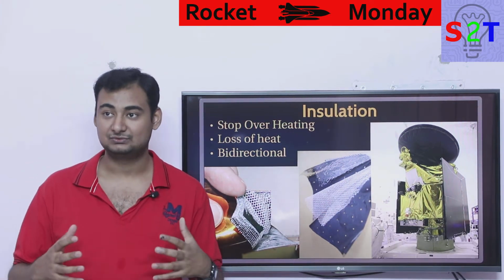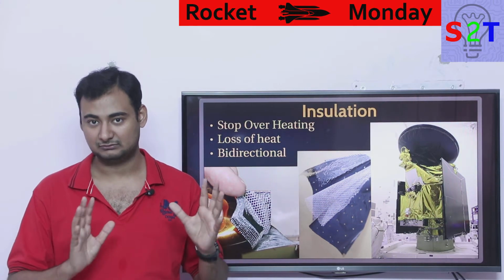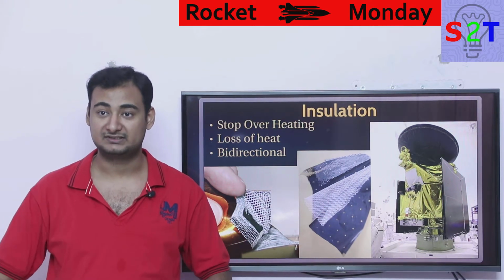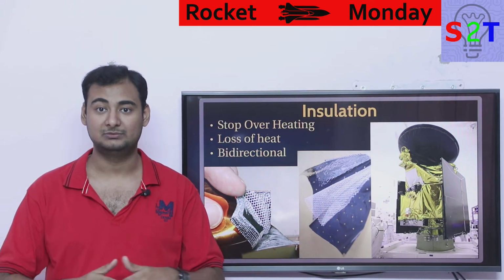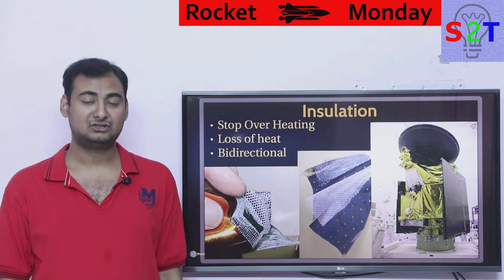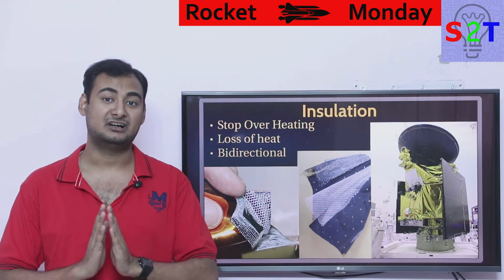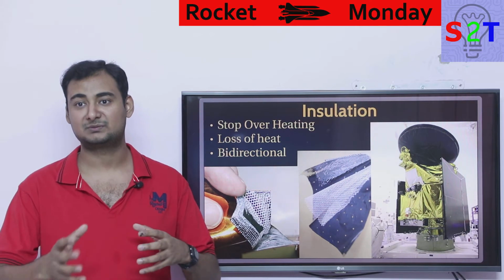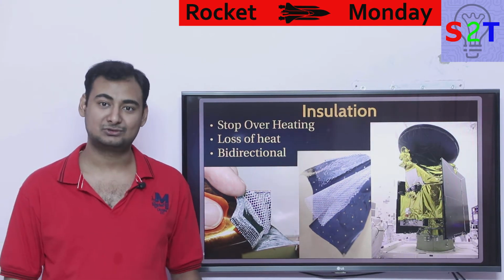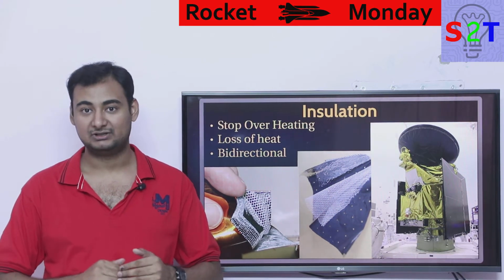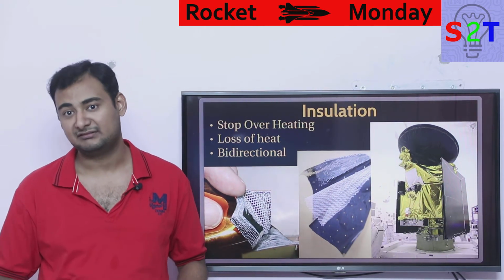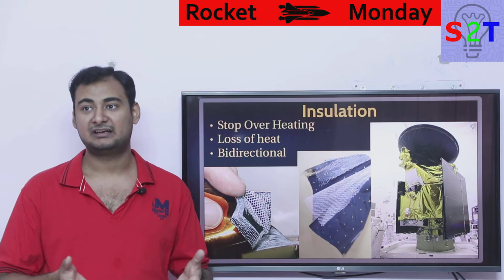And that is why a space suit is built for operation with a human. They have a lot of cooling systems. They have a lot of water circulating to keep the astronaut cool, because an astronaut by default, even if not doing anything, like sleeping, will be generating 100 watts of heat. If your insulator is not leaking that kind of energy, the astronaut will be cooked inside. So you have water circulating, and that water dumps its energy either in another water reservoir, it may have another cooling system, or it may have a thermal bank.